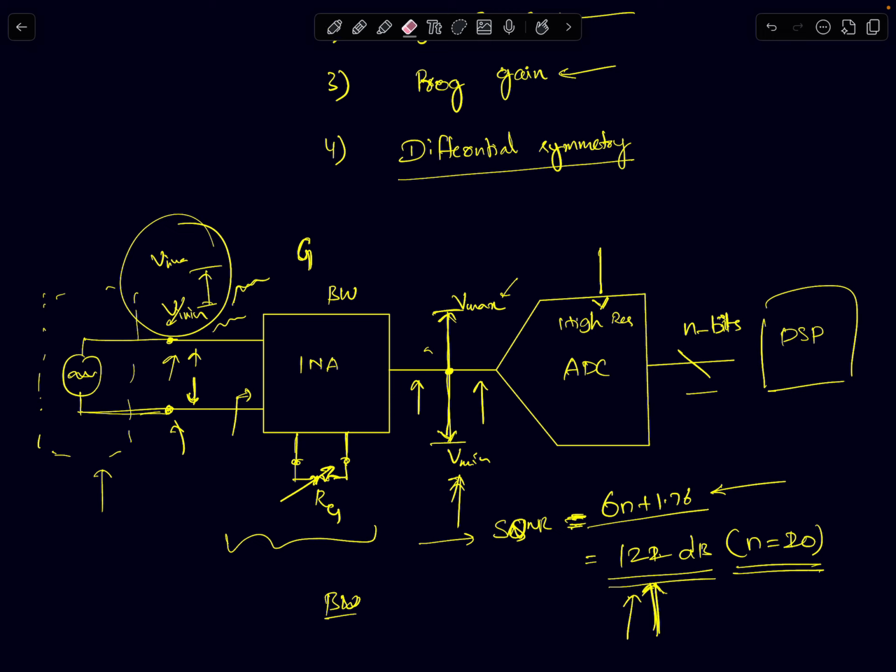If the input signal changes by a small amount, like a sudden step change from 0 to delta V, the output is going to undergo some settling. Okay, it will settle to the final value, delta V times the gain. That should settle within a few time constants, so that the ADC, when it is sampling, samples the changes as well. So bandwidth matters as well.